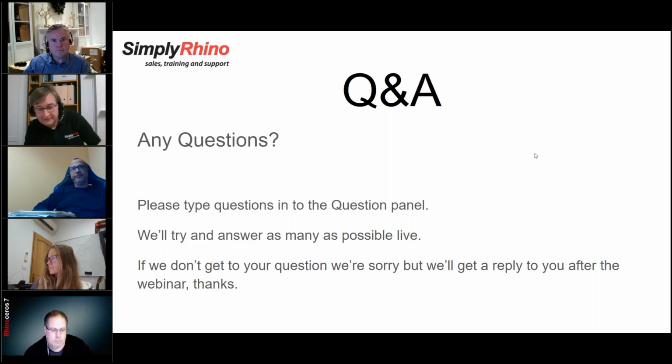Yeah, the pull command is very powerful as well. For example, if you have used QuadRemesh to simplify a scan and then you want to modify that scan, pulling to another surface or another mesh is very powerful. We've been using that in training the last few days, and it's really good. Okay, great, thanks, Andy.